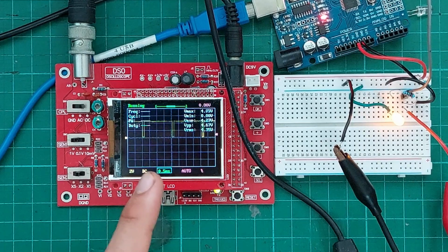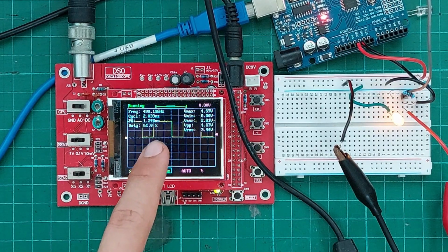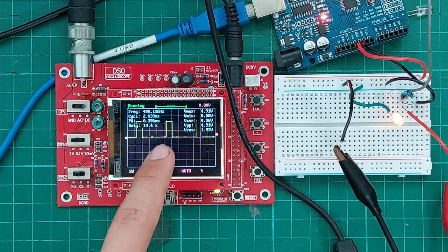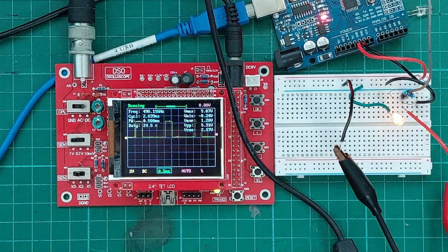Okay, so when it's at the maximum brightness, see that the line is all the way at the top, and when it's at the minimum brightness or off, it's all the way at the bottom. So this change in duty cycle basically controls the brightness of the LED by turning the LED on and off so quickly that our eyes can't really see the individual switching, and we are tricked into thinking that the LED is actually getting dimmer and brighter.